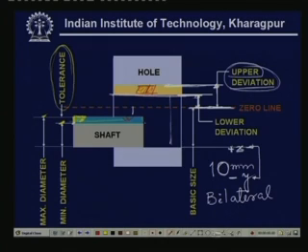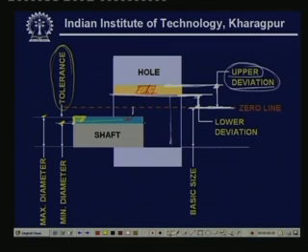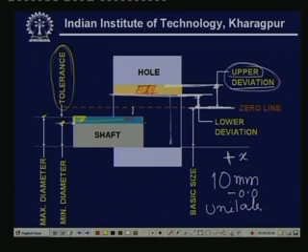And in case you give the same dimension once again, 10 mm, having minus side 0.0 and plus side say x, then it refers to a system where only on one side you are giving the tolerance, and that is sometimes referred to as unilateral.